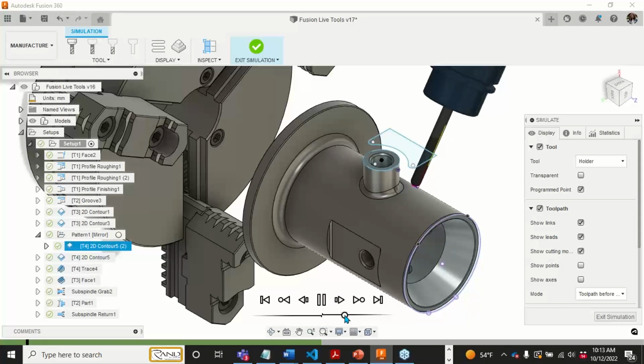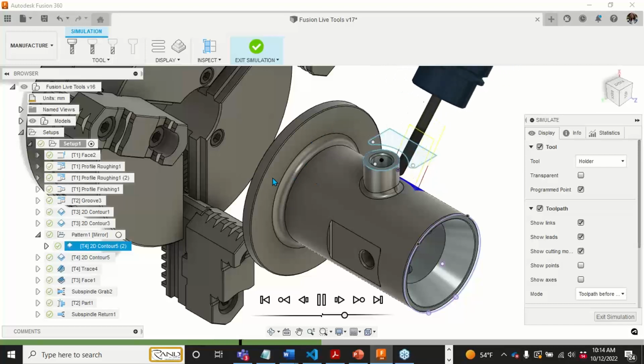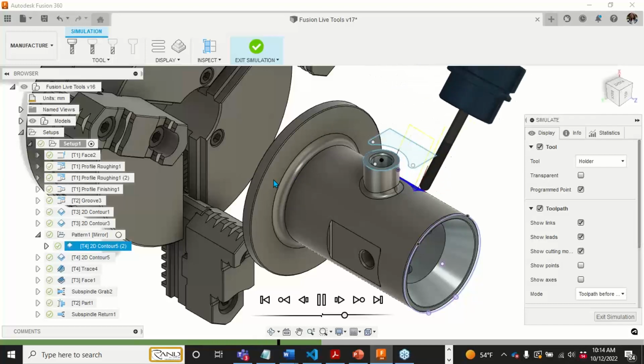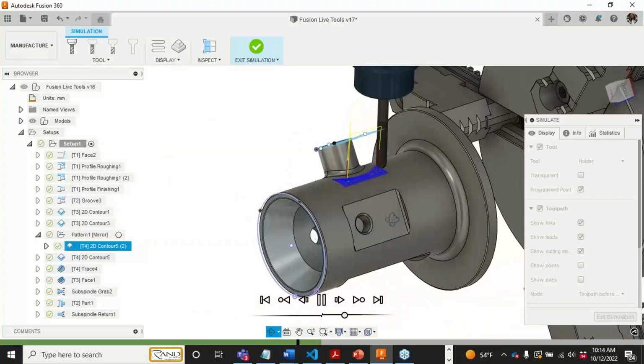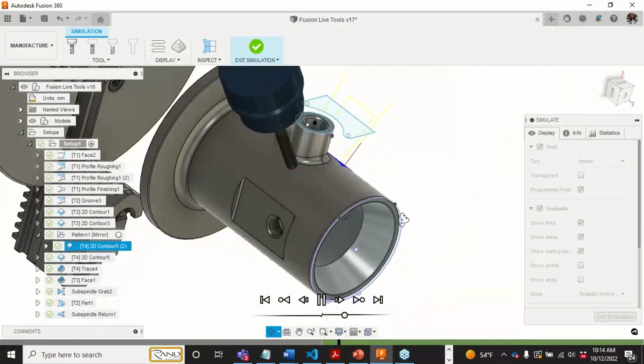We can see the movement of our tools coming down, and because I have the ability to move in both X and Y and rotate about the Z, this machine automatically becomes a very brilliant multi-axis machine where I'm able to get a really nice cleanup toolpath to finish this boss out.